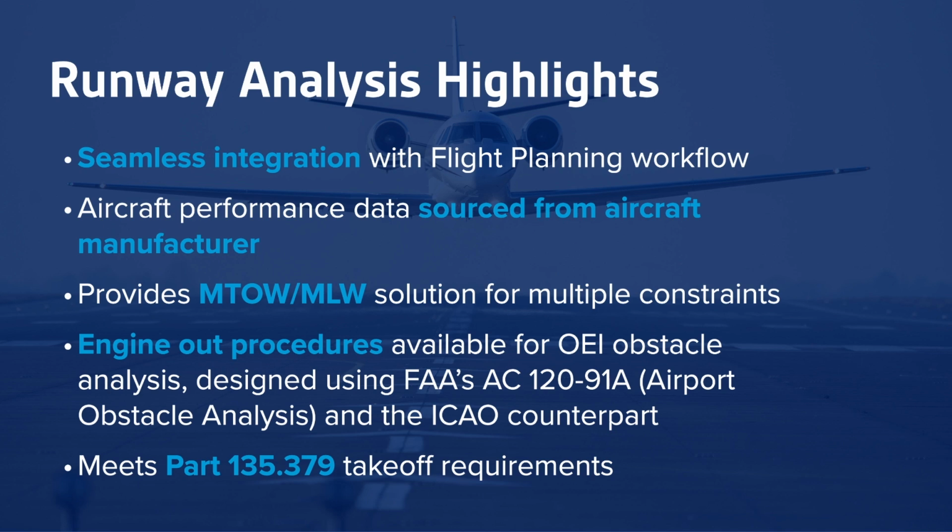The other bullet to point out is we're providing maximum takeoff weight and landing weight solutions for a range of different constraints. As you modify runway and runway slope or the aircraft weight, we're going to tell you when all sorts of limits are hit. One of the things I have experienced flying frequently with short legs and flying into mountainous airports are simple things like tailwind limit exceedances, but also brake energy limit or go around procedure limitations as well. So you'll see all those errors pop up in the application as you exceed those.